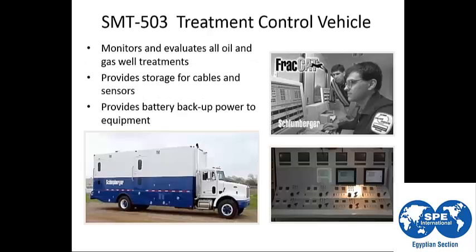This is the monitoring unit. This is the control panel for the pumps. Here we have 8 panels, one for each pump. You can control the pumps from this unit. Also, this screen is showing you, and you control from this screen, the rate of each additive during the job.